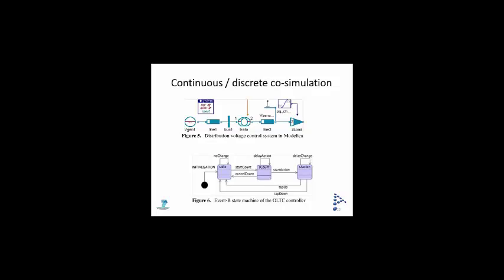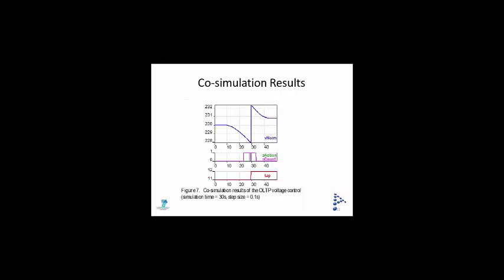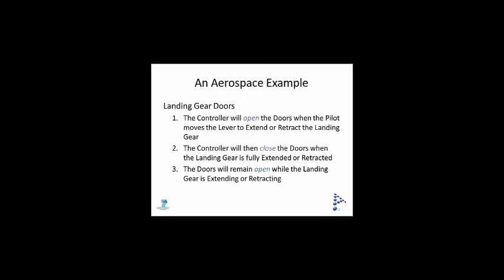And this is a state machine. So the engineer describes the state machine with some notion of timing, which is going to control this. And we model this continuously. And then what we're able to do is simulate this. So this is at the back-end verification. We can model as the voltage drops from 230 down to 228, which is the limit. Then the controller can institute a tap change. The voltage can go up again. So that gives you a flavor of how that works.